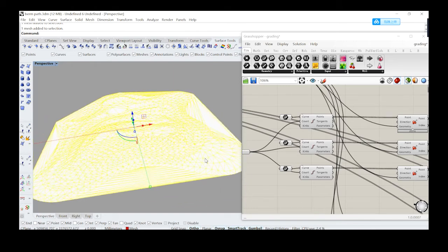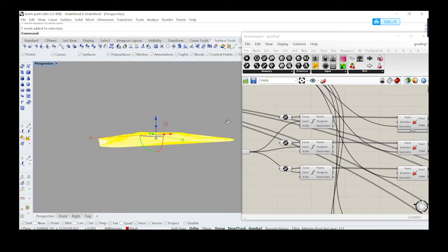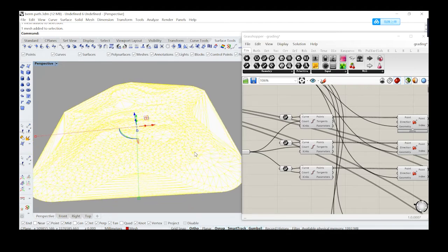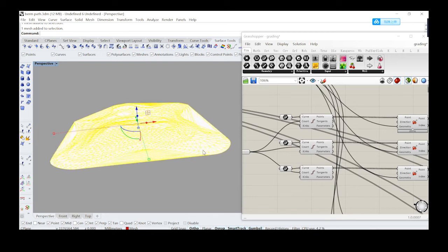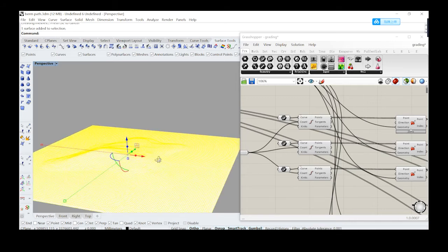And because mesh in Rhino is relatively difficult for further adjustment and manipulation, so we need to transform this mesh into a surface. And we'll do this by typing the option drape, and it's basically the simulation of gravity, so it's very good for making landforms. And note that we can adjust the accuracy of fitting by choosing the spacing number. Alright, now we got our surface done.